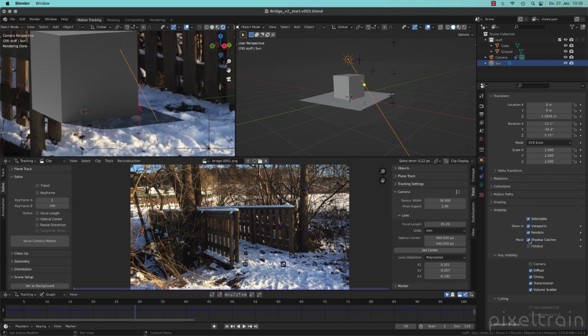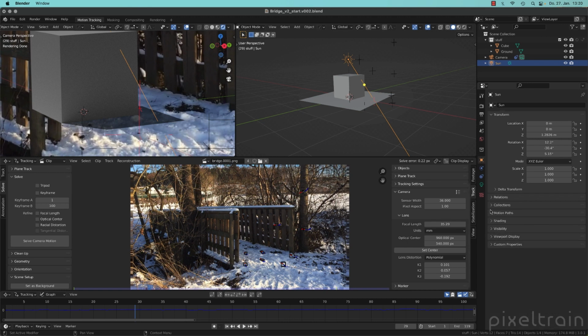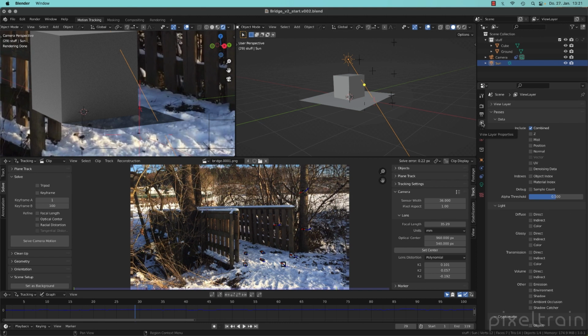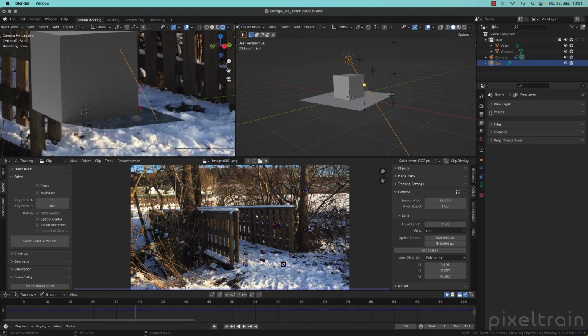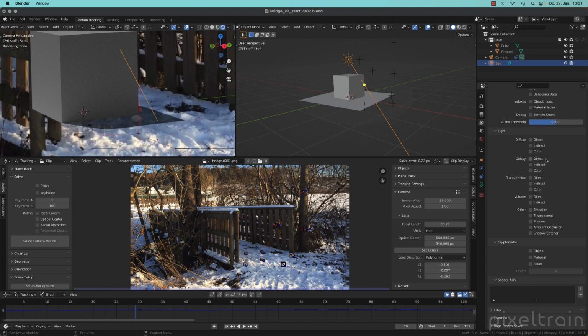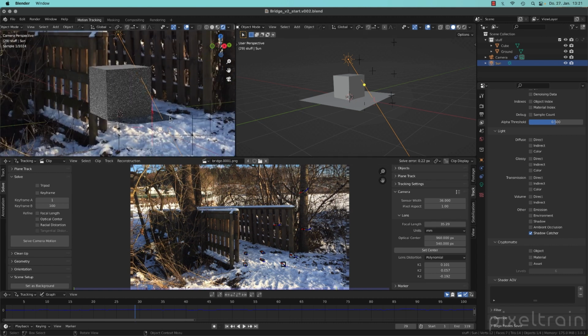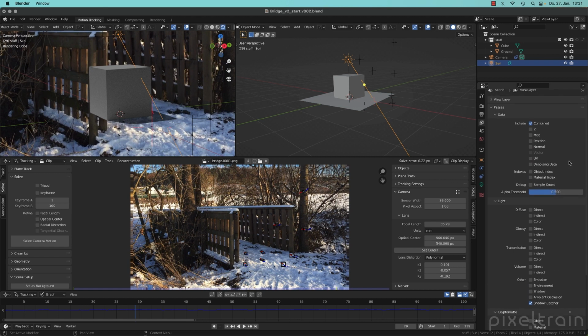Activate that. And another thing which is inside of this Shadowcatcher setup in Blender 3.0 is if you work with render layers, which we deactivated, you remember, but if you work with them, you can go here into the passes, go down, down, down, and here is now a new Shadowcatcher pass. The moment you tick that, it can happen that you don't see your shadows anymore.